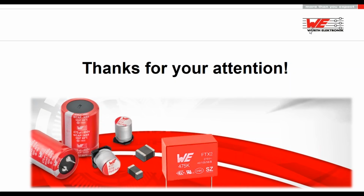There's a pretty wide question. What are the failure characteristics of different caps? Sadly for this session, maybe it would be a good webinar topic, because the failure characteristics can be pretty different. It's a good question. Mostly for the MLCCs, you cannot say if it's open circuit or short circuit. You can have both. By bending and cracking, both are possible.